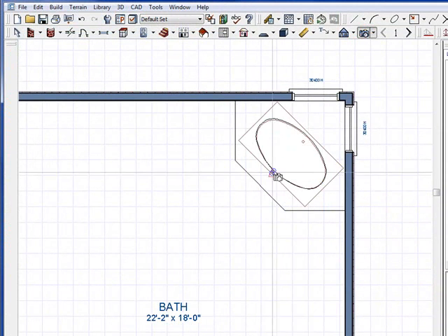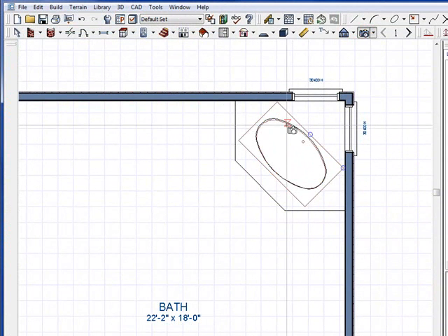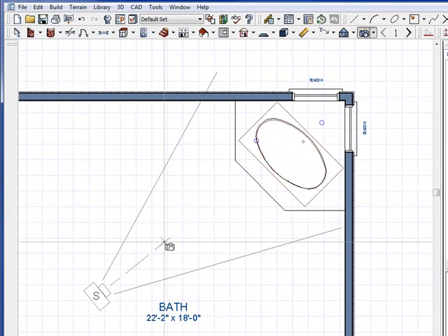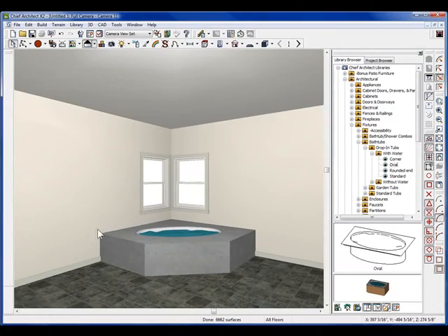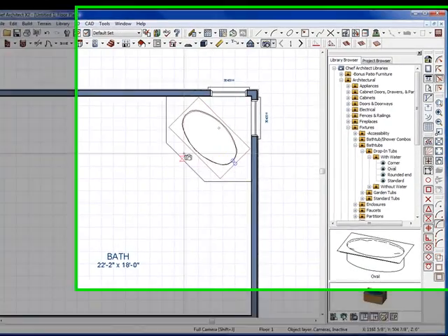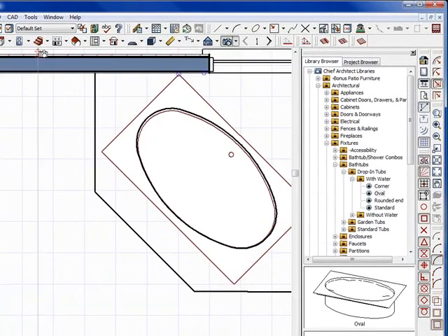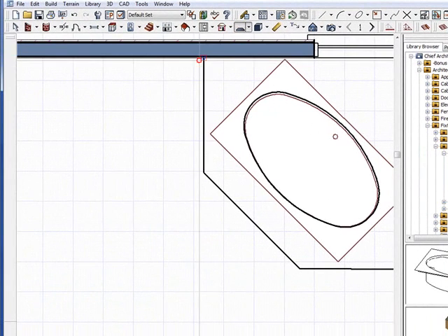And what I've done is I basically made that oval shape a slab, and then I told it to be a hole instead of a slab. And it'll generate a hole in whatever slab you have. And there you go. So you can probably guess how I'm going to make the step as well. Well, let's keep using that slab tool.